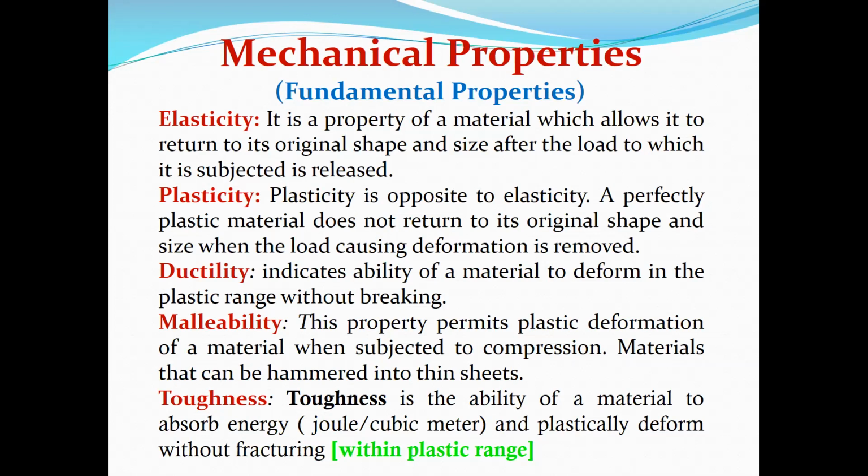And ductility indicates the ability of a material to deform in the plastic range without breaking. That means after the elastic limit, when the plastic state starts, the material will be subjected to deformation. So ductility is an indication of the deformation that continues before the material breaks.